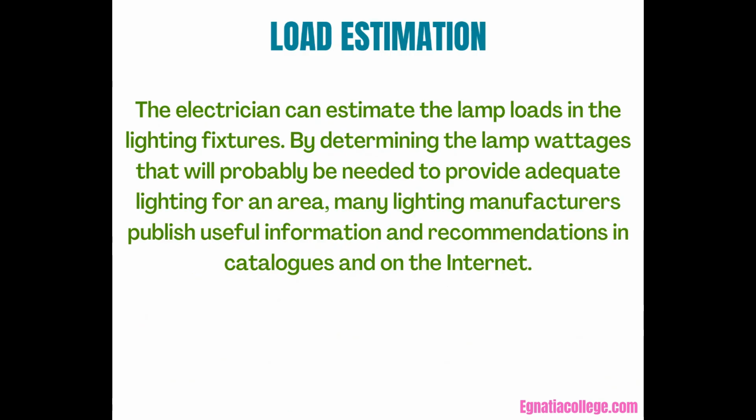Load estimation. The electrician can estimate the lamp loads in the lighting fixtures by determining the lamp wattages that will probably be needed to provide adequate lighting for an area. Many lighting manufacturers publish useful information and recommendations in catalogs and on the internet.